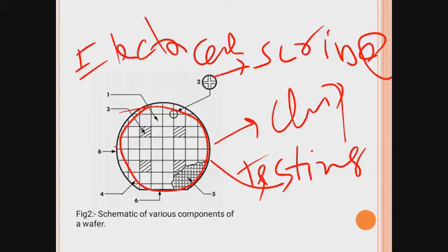For example, for 300 millimeter wafers this translates to a total of 440 dies including edge chips, while with 450 millimeter wafers the total number of dies is 994. I got this information from the area of wafer divided by area of die calculation.